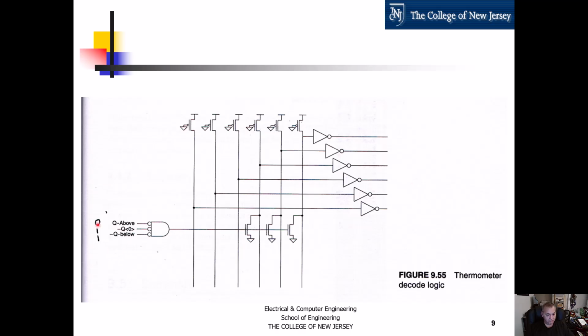So in front of the 64 NOR gates, we have these 64 Q and Q naughts. Each NOR gate is going to correspond to the circuit that we just saw. Now this input is going to be tied to the Q naught of the one below, the Q naught of the circuit that corresponds to the NOR gate, and to the Q above.